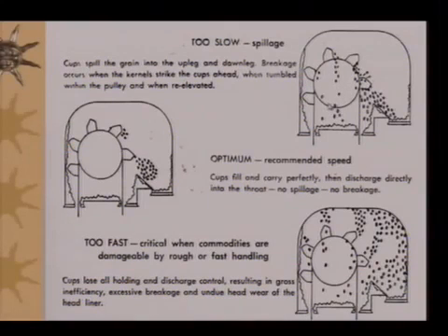of grains. And if you are operating your machinery at too fast a pace, if the speed is too much, then what happens here? Cups lose all holding and discharge control. See here, material goes helter-skelter all through, and then again here you find excessive breakage and undue head wear of the head liner. But if the recommended speed is used, you will find cups fill and carry perfectly, then discharge directly into the throat, no spillage, no breakage. So this should be kept in mind, that we must operate our bucket elevators at an optimum speed while handling